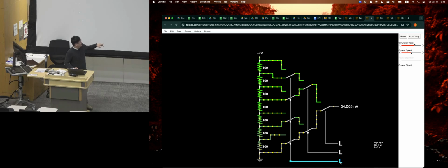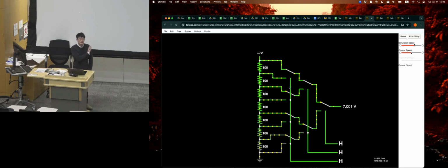But anyway, once you turn 1 bit on, that gives you 1 volt, and then the next bit gives you 2 volts, and then 3 volts, and then 4 volts, and so on, all the way until you reach whatever amount you have on the V reference. So this is a pretty straightforward design, and the challenge here is obviously the same as the flash ADCs.